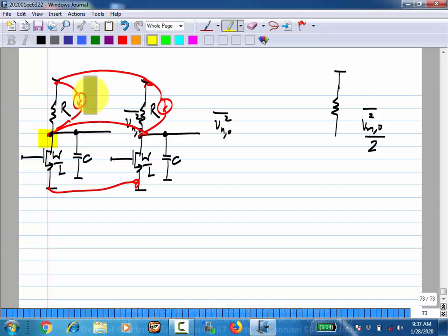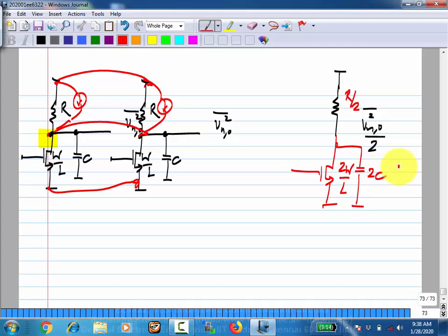This is a very fundamental thing. It is not related to any specific circuit. With any circuit this happens. This is known as impedance scaling. To have lower noise, you should have lower impedance levels. Instead of R, you have R by 2, and instead of a MOS transistor of width W, you should have 2W. You may have to do this because your initial design many times does not satisfy the noise specifications. You simply have to scale the circuit so that it works.